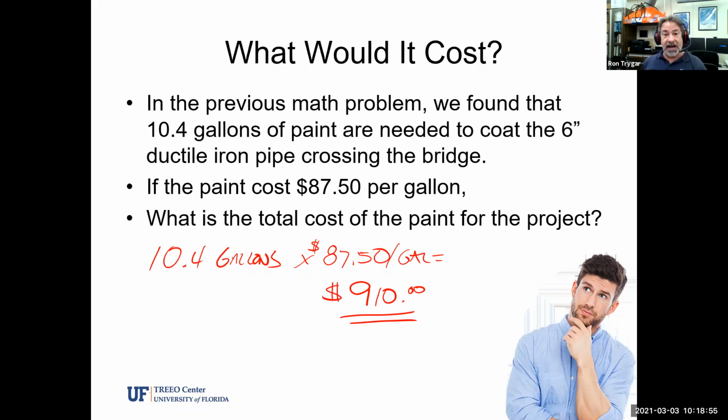If you're contracting somebody to do this for you and you don't want to go out there and hang off the bridge and paint this, then this particular calculation will help you know how many gallons of paint would be needed, so that you know how much to budget for and how much the contract quotes that are coming in to get the job done should be, based on how many square feet need to be painted. If you don't know how to calculate this and they put in some number on there that they estimated and they're way off, you could be in trouble.